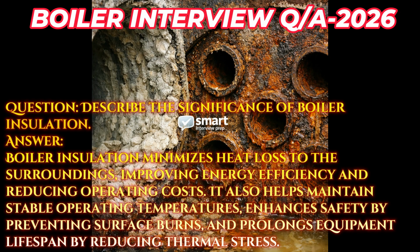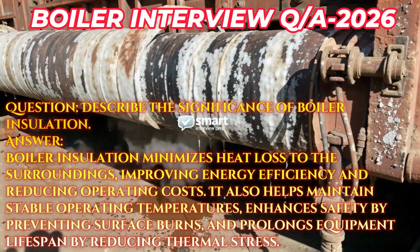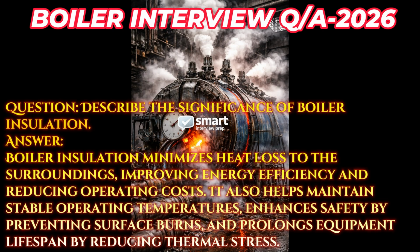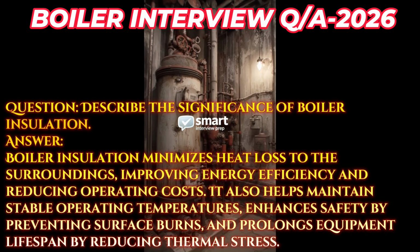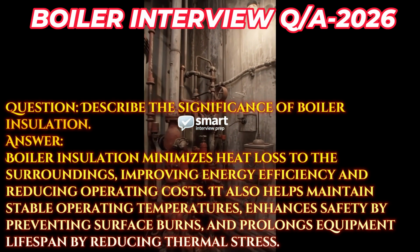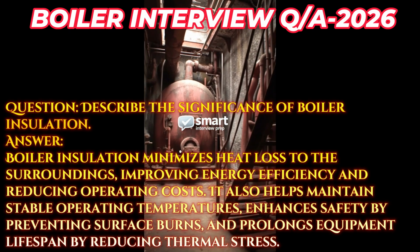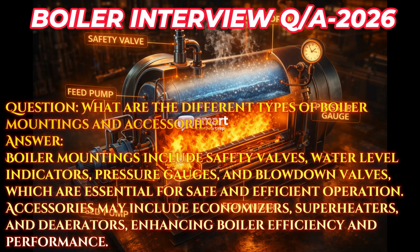Question. Describe the significance of boiler insulation. Answer. Boiler insulation minimizes heat loss to the surroundings, improving energy efficiency and reducing operating costs. It also helps maintain stable operating temperatures, enhances safety by preventing surface burns, and prolongs equipment lifespan by reducing thermal stress.